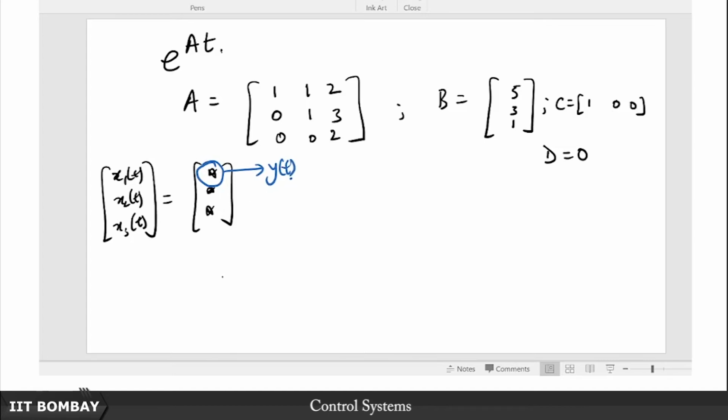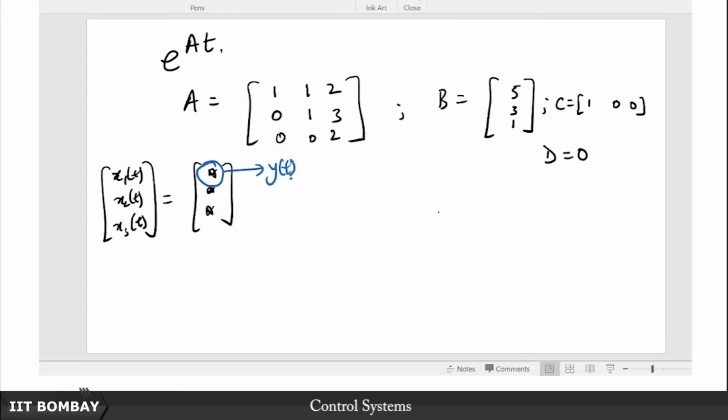So in this problem I will solve for this x, and there is another claim that I am going to make. Notice please that I am not going to use Laplace transform at any stage. The other day you remember when we took you to this diagonal form or this block Jordan form, and then we said how do you get from this diagonal form to the exponential of this diagonal form, and we took this Laplace inverse, right, because we said that once you have T inverse AT is equal to this diagonal matrix, then e to the T inverse AT is equal to e to the this diagonal.